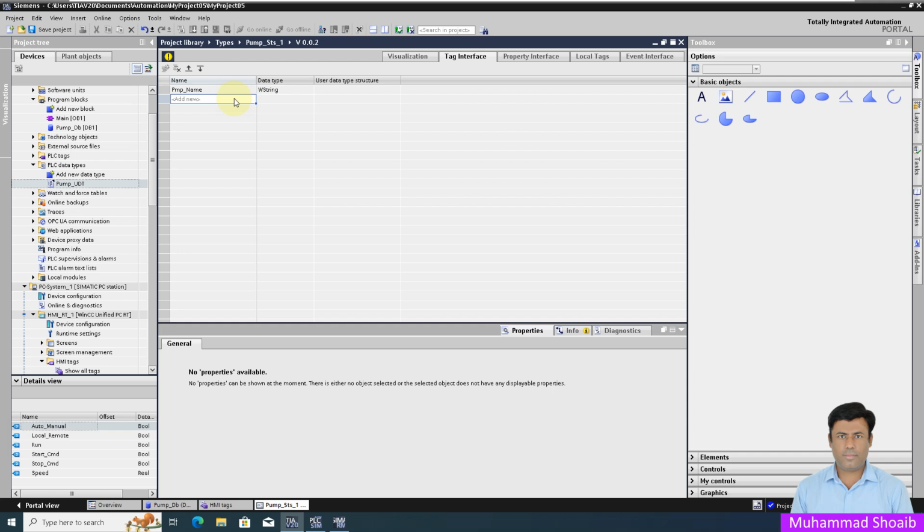So I will write the name here, for example, PMP. After that, I will come here to the data type and expand it and go down. You can find it here, the PLC UDT, and click here on OK.